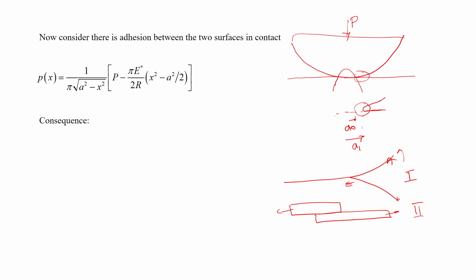So, the fracture occurs because of this tensile load that happens towards the edge of this contact area, or if you say fracture mechanics, this is a crack tip. So, what happens here is basically the stress concentration, because the stresses become singular at the crack tip, and as a result of this singularity, the crack propagates.